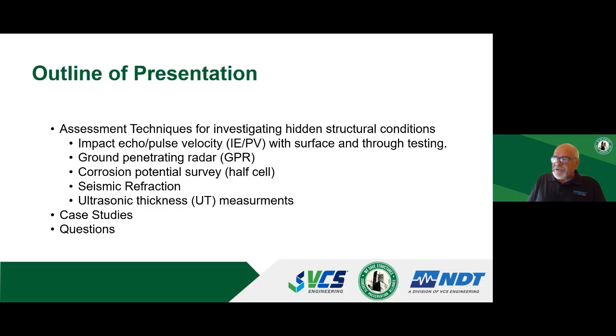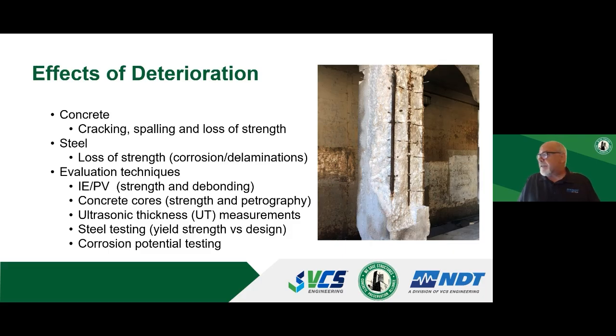A little more traditional geophysical test methods, seismic refraction gives us some general soil profiles and layers of a site, maybe before some of the borings are put in. Ultrasonic thickness testing for metal, whether it's a section loss of flanges or webs. We do a lot of anchor bolt testing as well with that technology. I've got a bunch of case studies to share with everybody, and you can see where these different test methods help investigate and quantify infrastructure. And of course, we'll have time for questions at the end.